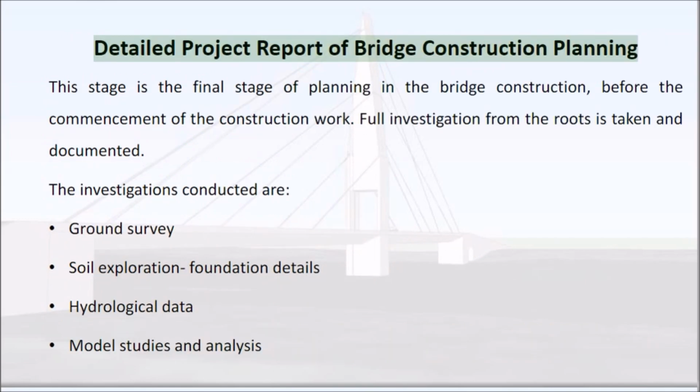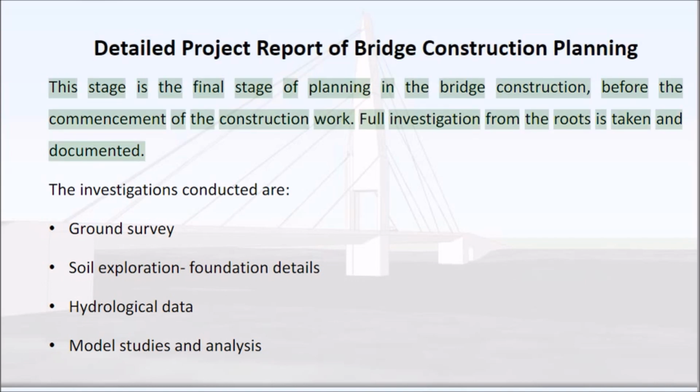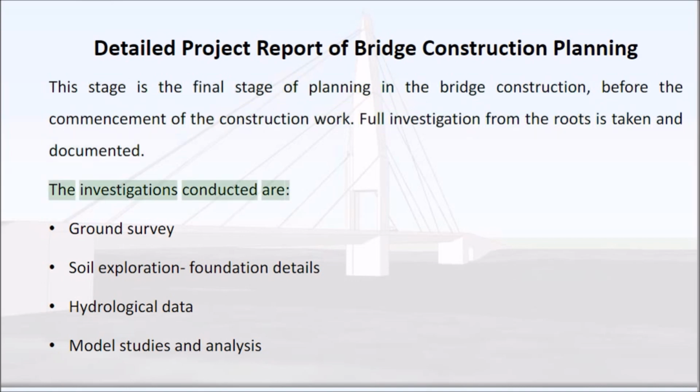Detailed project report of bridge construction planning. This is the final stage of planning in bridge construction, before the commencement of the construction work. Full investigation of the routes is taken and documented. The investigations conducted are: ground survey, soil exploration, foundation details, hydrological data, model studies and analysis.